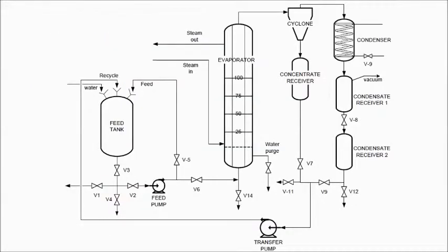Then, we move to the next step, which is to conduct the experiment. This is the figure of the climbing film evaporator. I'll be further explaining the parts as we go on. First, we have to open the valve for main cooling water supply. Subsequently, turn on cooling water valve to allow flow into the condenser. Ensure that circulating cooling water flow rate is 6 liters per minute.